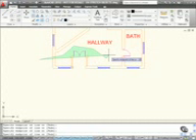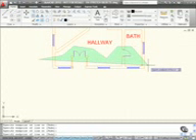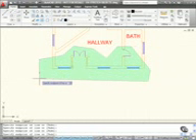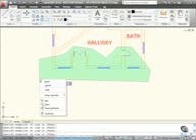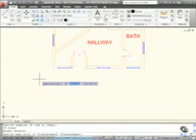Notice I'm clicking away here. It doesn't matter how many points I actually use. I'm going to come down through there because I don't want to stretch that bathroom window. Down here, across this way to here. There's my crossing polygon. So all the objects crossed in that polygon will be stretched. I then right click again and select enter to confirm the polygon and the objects in the polygon. I then right click again now to confirm the object selection in the stretch command. Two right clicks, remember that.